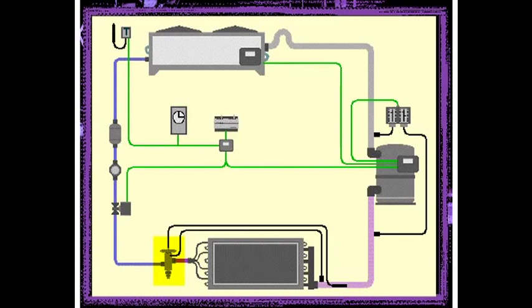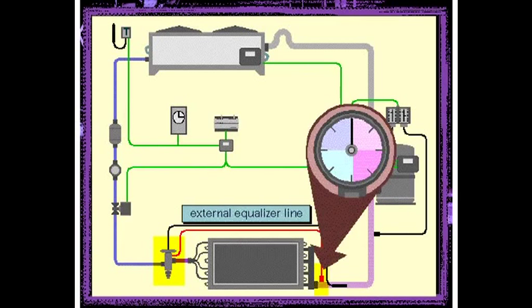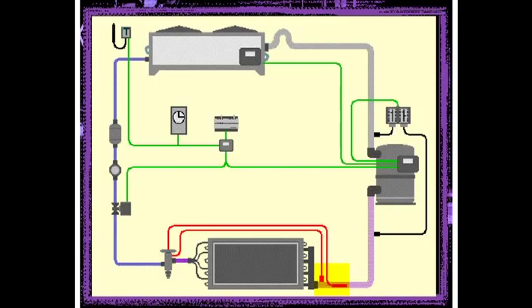You will notice that the expansion valve also receives a pressure signal measured at the evaporator outlet. This signal allows the expansion valve to adjust to the pressure drop in the refrigerant as it goes through the evaporator. This pressure drop lowers the evaporation temperature slightly and could give a false superheat reading if it were not compensated for. Under normal operating conditions, the level of liquid refrigerant stabilizes in the evaporator so that the flow of liquid is proportional to the amount of heat to be absorbed.